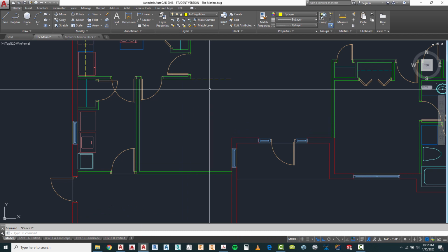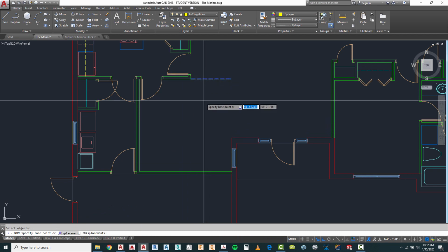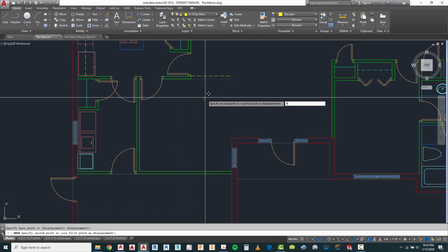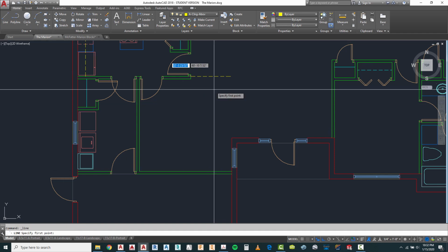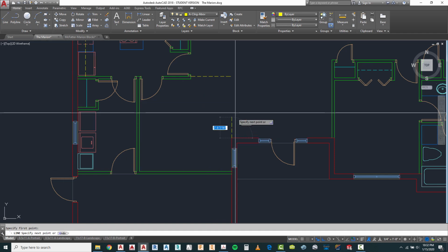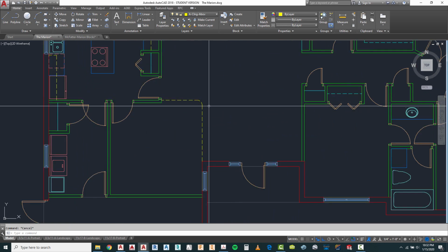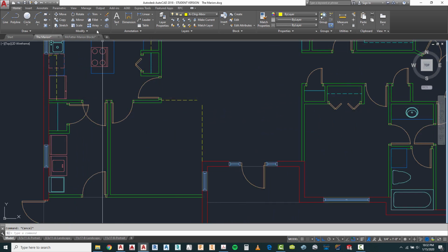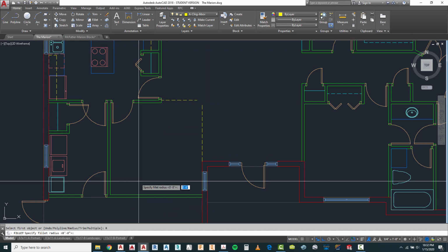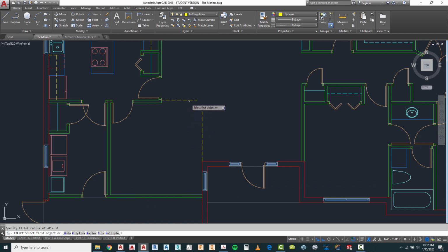So this actually needs to be about 4 inches further up, and I've got a line coming off of here. I'm going to fillet that. Now notice it still maintained the fillet that I had here, so I have to remove that. And now when I use the fillet command, I need to go back to radius, give it a value of 0, and then fillet without that.